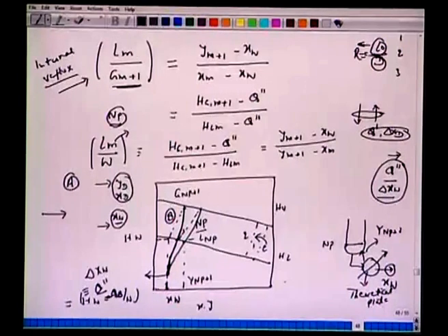So, again if you take the bottom plate which is Np, the vapor which reaches here is y_Np plus 1, and the liquid which leaves here is x_Np, and they come from the operating line. Vapor which reaches here leaves this plate, that would be in equilibrium with this.